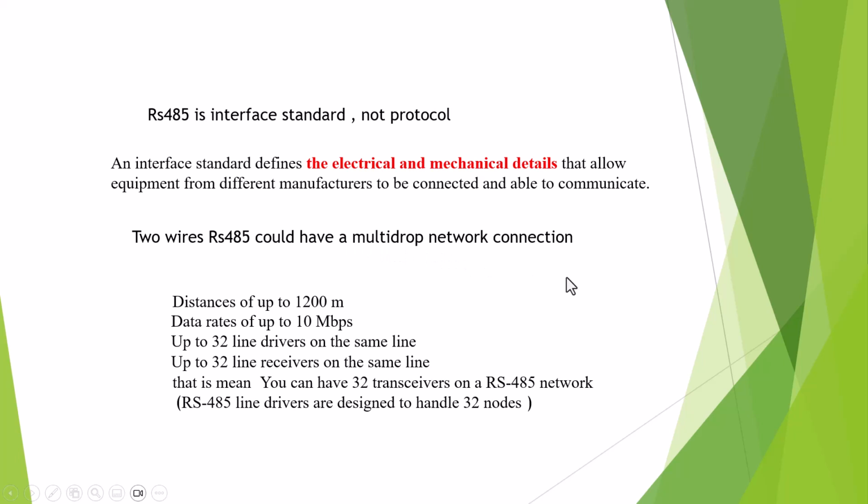If you make an RS485 multi-drop network connection, the maximum distance is up to 1,200 meters. The baud rate is a maximum of 10 Mbps.